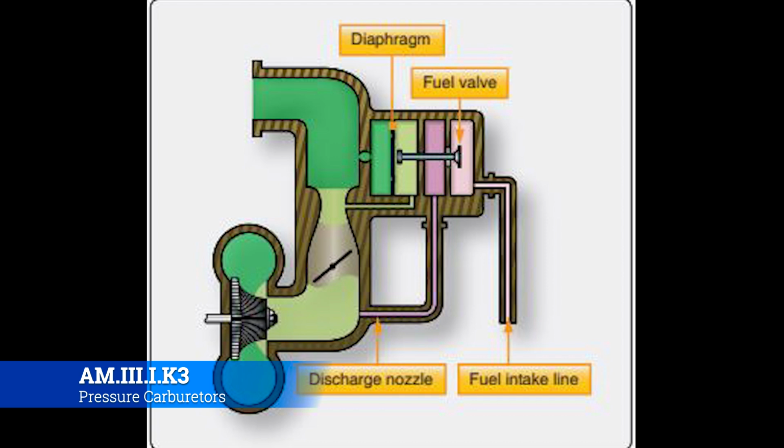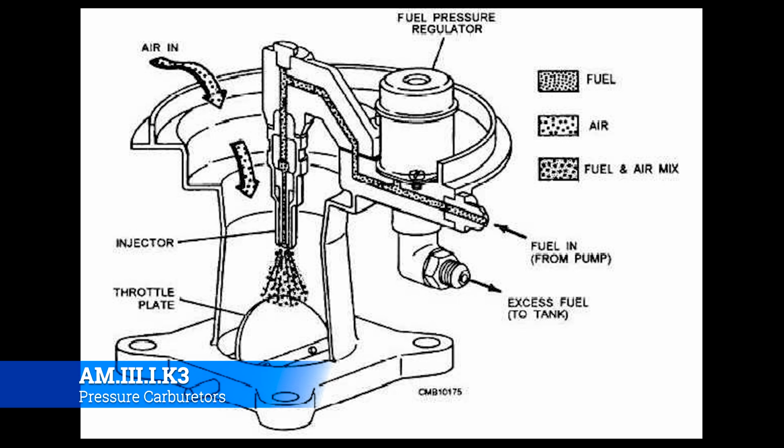So let's first talk about the throttle body. All right, the throttle body is pretty straightforward. It's all the things that you think of whenever you think about a carburetor. It contains throttle valves, the venturi, a boost venturi, and an impact tube. All the air entering the cylinders has to flow through this throttle body, and so it's controlled. It's the air control and measuring devices. It's what keeps the engine running at the rate you want it to run. Whenever you set your throttle, you're actually moving the throttle plate down there, and everything else happens downstream of that control input.